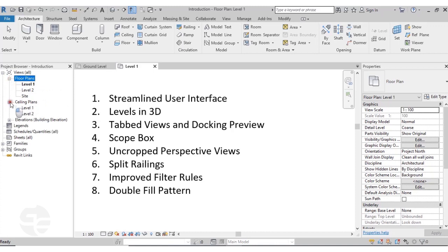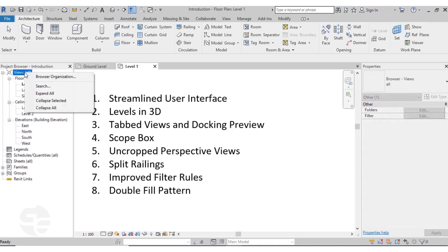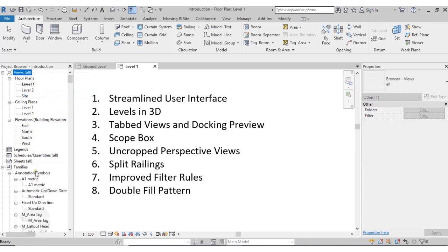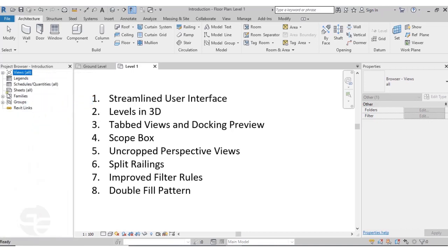But we had to do this individually for each branch and sub-branch. But now in the latest version, we can just right click on any option here and click on expand all to expand all the branches and sub-branches given in the project browser. Again, to collapse them quickly, you can just right click and say collapse all, which will collapse all the branches and sub-branches which are by default or have been created by us.